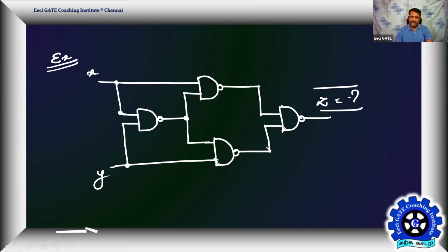Fine then. We are already into the core of digital electronics. We started making SOP implementations in the name of the exclusive OR function, and started giving you the fundamentals of AOI implementation as well as pure NAND solution. Similarly, tomorrow we'll take a POS expression and see how to make it a pure NOR solution. As a front-end digital designer, you should always know how to implement an SOP function and a POS function. Then we'll get into the applications later. Now itself we are in an application: the exclusive OR implementation.